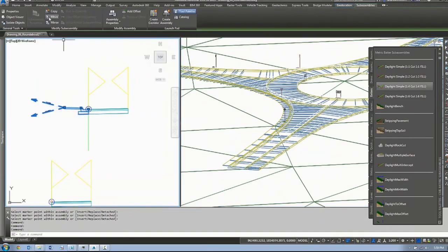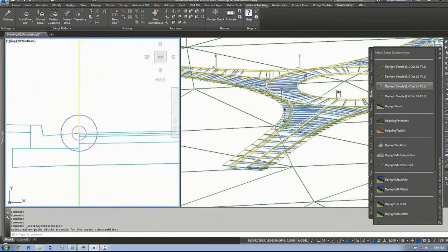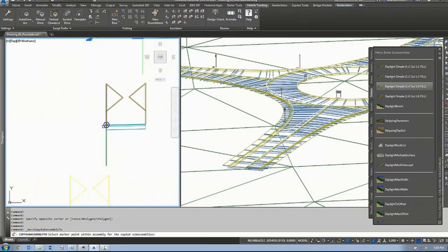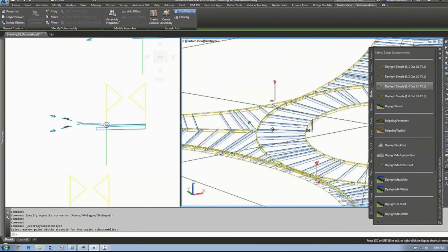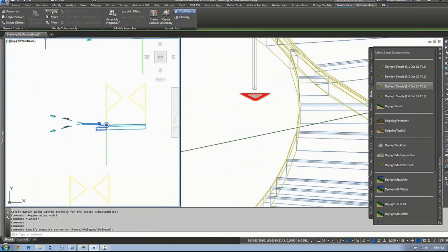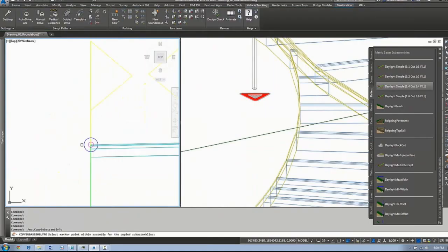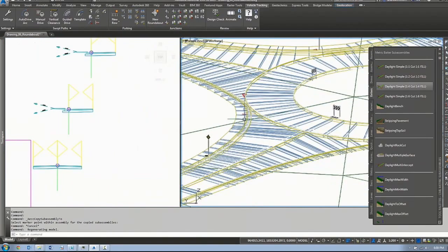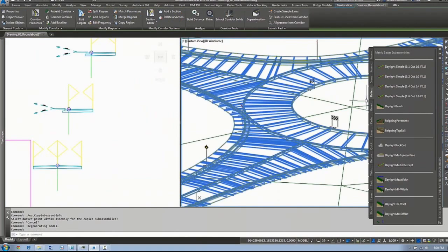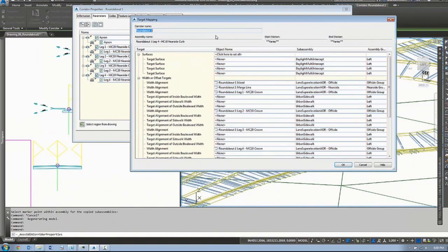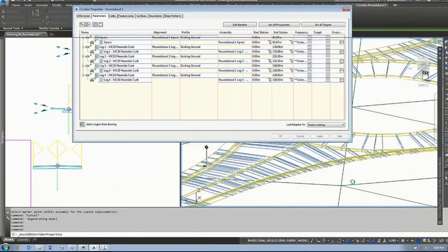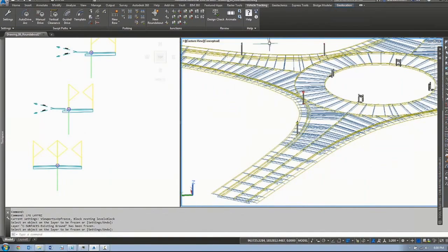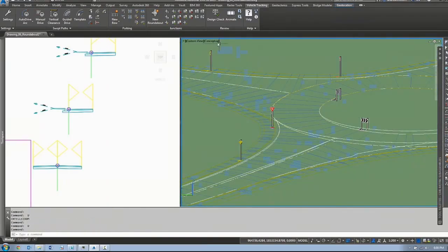And as we do that, you can see on the screen there, everything's just updating in real time. Now, what I need to do is just set up some targets. I'm now going to copy those parameters to each leg of the roundabout. So just copy those again using the standard Civil 3D tools, and it goes and builds out the geometry for us. Copy, put it into place. Once again, really straightforward process. What I haven't done there is actually assign my final earthworks targets. Then we can actually come, assign our surface targets, fix up the batter slopes so we know where everything's going to daylight.